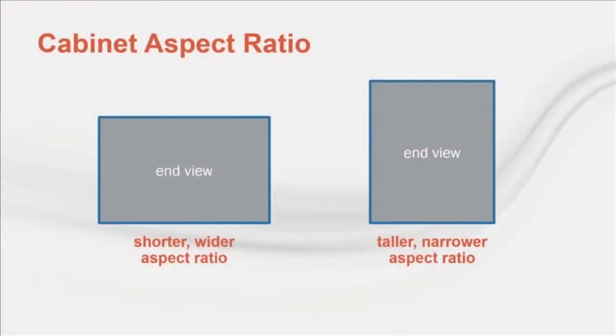Historically, cataloged air handlers have been designed to a fixed aspect ratio, width versus height. But more recently, a trend has been to offer some variability in this aspect ratio to better meet space restrictions on a job site. That is, you can select an air handler that's short and wide or tall and skinny. The challenge is that the spacing between components, such as the distance between a cooling coil and the fan inlet, or between the outer edges of the fan impeller and the surrounding cabinet wall, impact fan performance and efficiency.